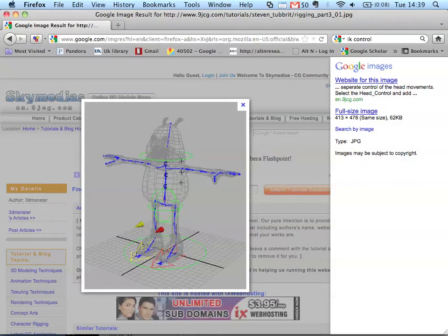Inverse kinematics goes in the opposite direction, not surprisingly. So what happens is you make control handles. Instead of saying rotate shoulder, rotate arm, you literally put a handle on the wrist, move the handle, and everything up the chain responds, right? So you just move the point, and it targets the chain to wherever you want to get to. So, how do we do that?